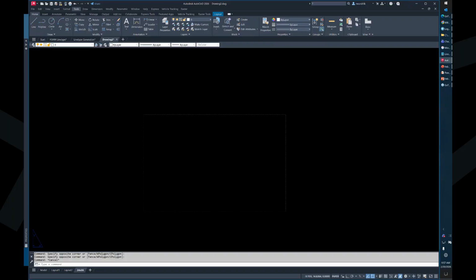Then it will typically work. If it's not printing them correctly through the sheet set, in some cases it's because a custom profile may have pathing that you can't see, and that causes it not to plot correctly. Again, that's something we would have to look at.